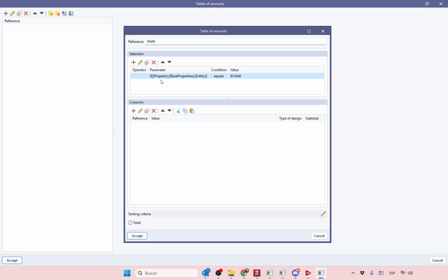It's quite similar to the process that we usually do when we are creating the rules for measurement to connect the BIM model with the cost database. So we can also select elements from the BIM model. Here is the same situation. We can even mix different selections here, for example, all the walls and all the slabs. This is not the case, but you can also add more lines here and then use the operator and or to combine them.